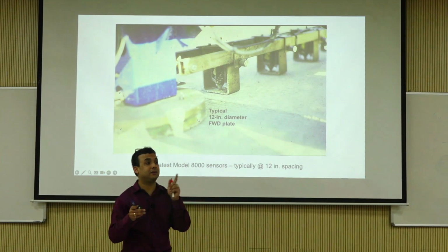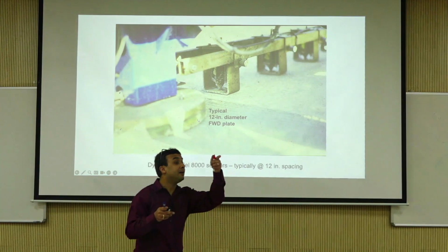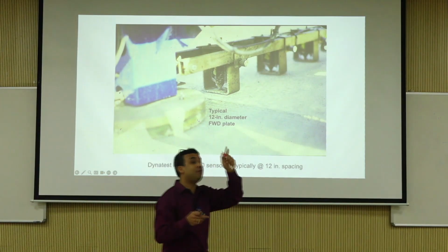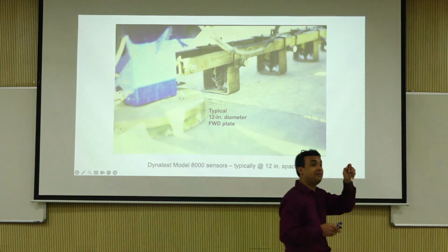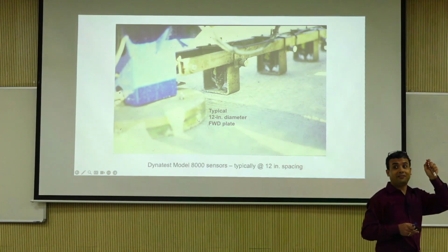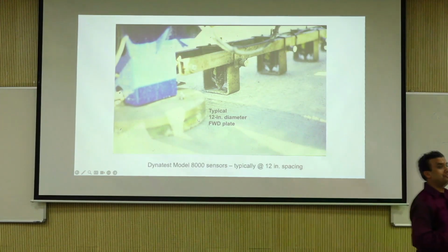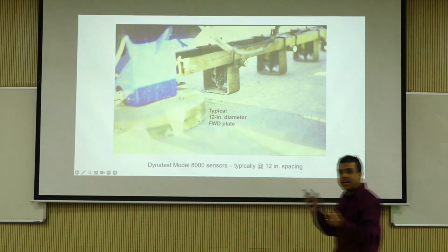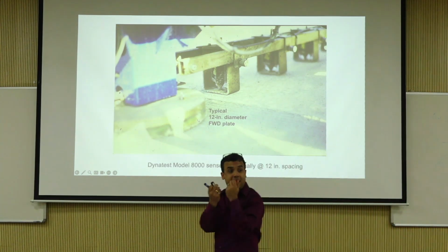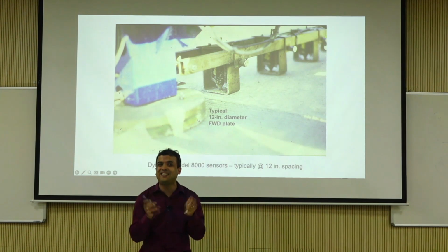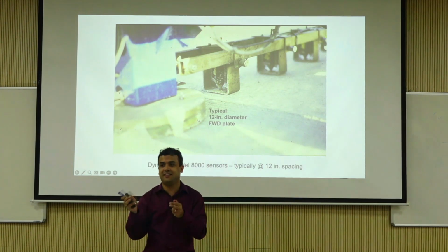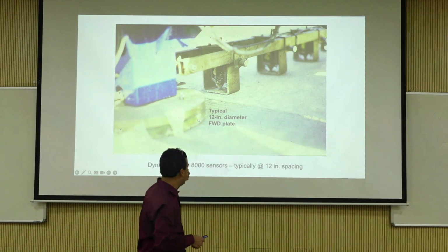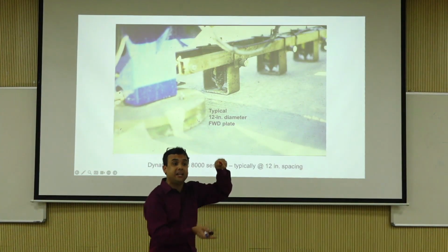They're not acceleration. What do they do? No, geophones don't measure deflection. Geophones measure velocity, so you have to single integrate them to get deflection. So there are two different types of sensors, right? There is another type of sensor that is based on LVDTs, and they don't call it LVDTs, they call it seismometers. There is a device called QAB that uses a seismometer that gives you deflection directly.